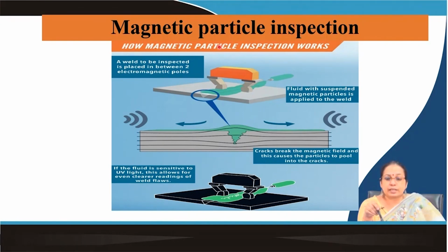So this is a typical weld zone where you apply magnetic particles on the surface, and then you apply a permanent magnet or a temporary magnet over there. We will see that the magnetic particles get aligned based on the direction or the area covered by the magnet, and if there are any flaws or discontinuities on the surface, the particles will not be there in that zone.